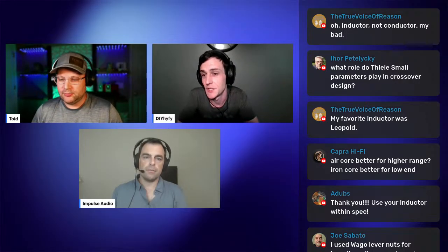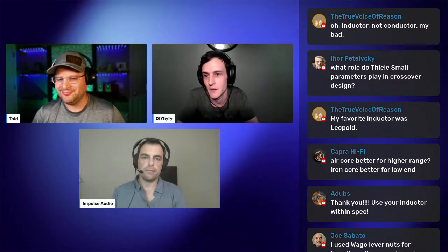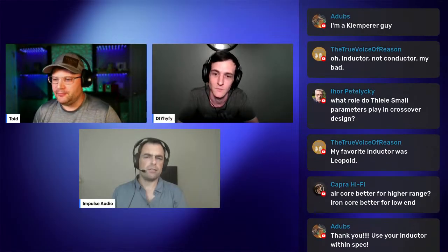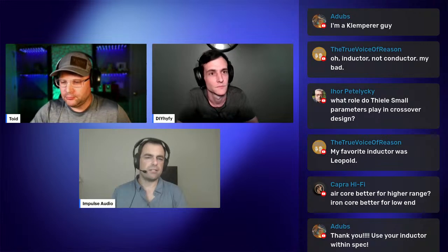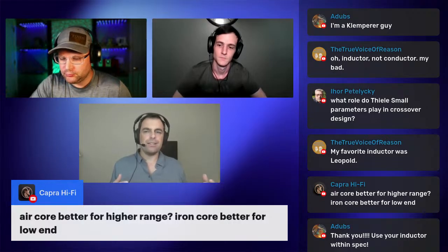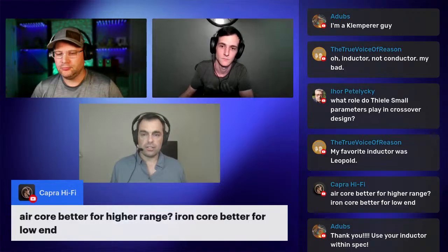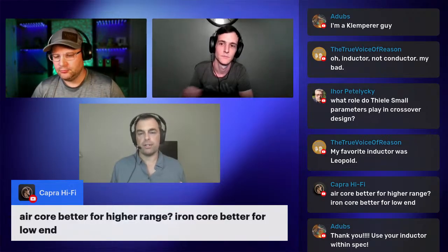And just since you held them up, most commonly an iron core inductor or that steel laminate core is going to be used in a woofer circuit just for traditional reasons. You might get bullied if you use that in your high frequency circuit, but they're really good for woofer circuits for sure. Well, Capra asked that question basically, and I was just going to say that it doesn't technically make a difference, but because woofer circuits generally require a large inductor, the cost gets crazy for an air core.